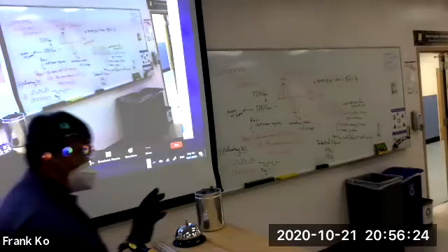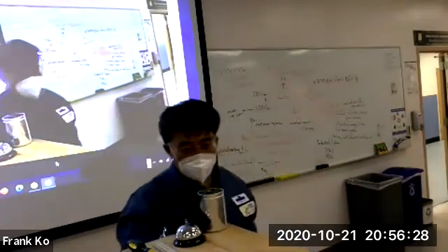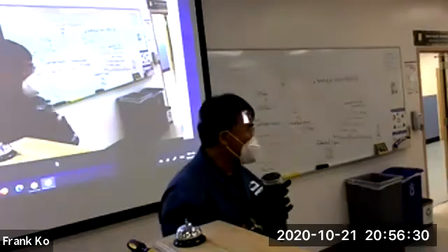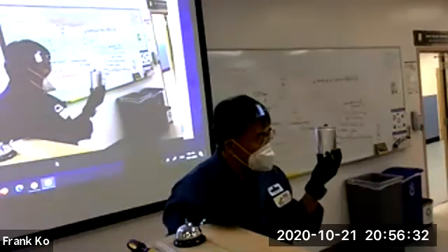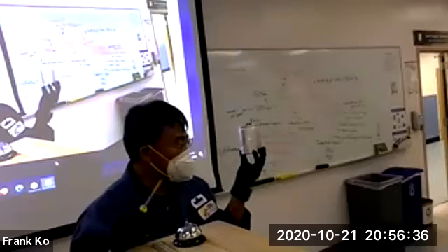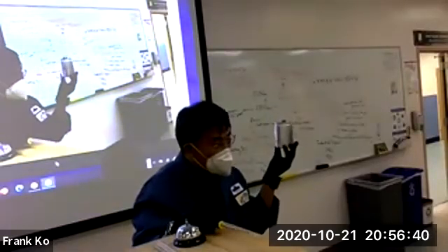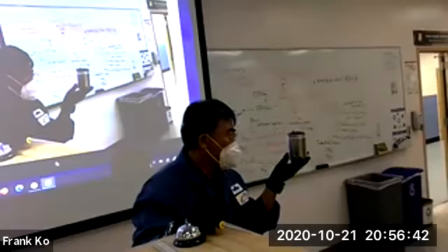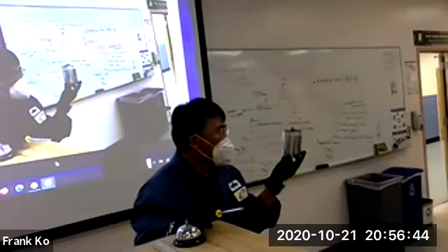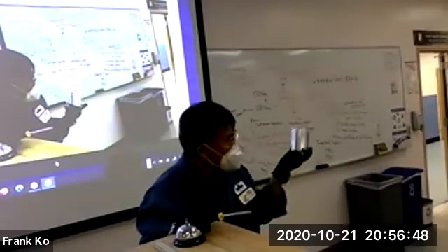Okay, so before we go to hook up our capacitors onto our boards, I want to teach you to pay utmost attention to the polarity of your electrolytics. What happens when you hook up an electrolytic capacitor backwards to a voltage source? It can explode if you hook it up backwards. If you hook it up forwards, it'll charge. So I hooked this up to 60 volts and I've charged this, even though this has a capacity of 200,